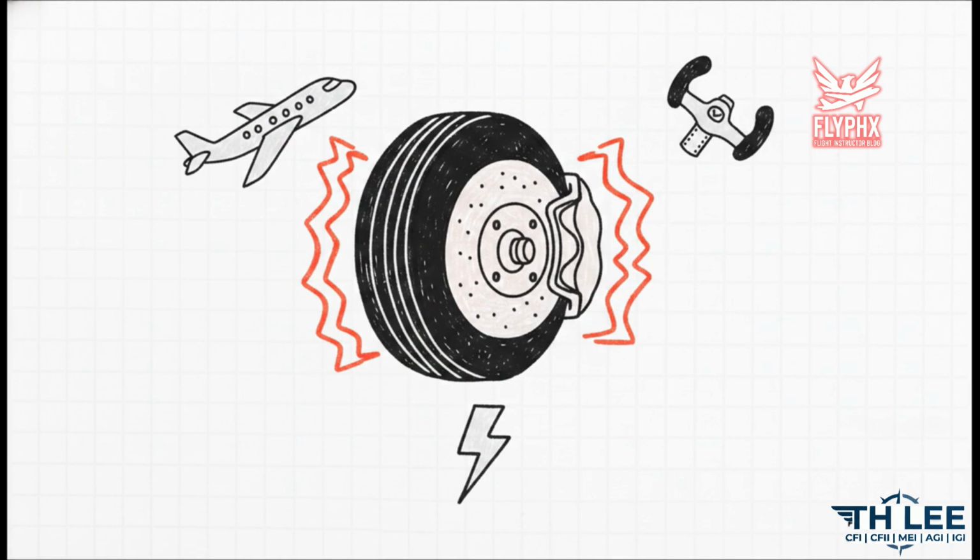Moving slightly beyond the propeller, the core subcomponents of any airplane are going to include the airframe, the electrical system, the flight controls, and the brakes. The electrical system is what generates and distributes power, typically using engine-driven alternating current, or AC, generators, auxiliary power units called APUs, and external power on the ground. All of this feeds vital systems like your anti-icing and avionics.